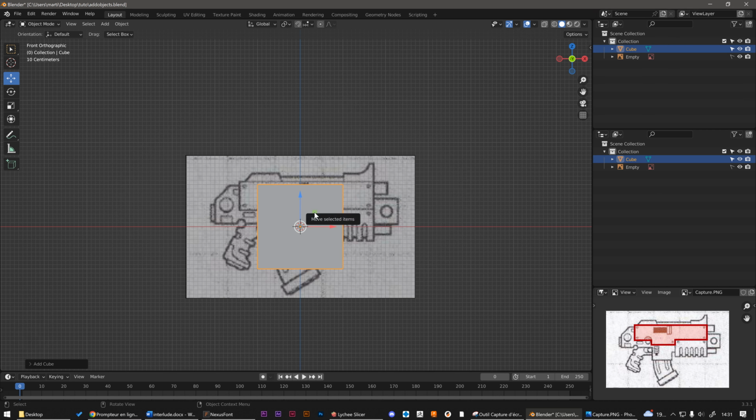So I will go back to the Move tool. We will use the Move gizmo when we move an object, but for scaling, we will use shortcuts. So remember, we can do a uniform scale with the S key. So first, I'm just going to scale the cube in order to make its height match the drawing. Then I center the object, and then scale it only along the x-axis to increase the width. So I use the S then X keys to trigger scale transformation along the x-axis and make the width match.